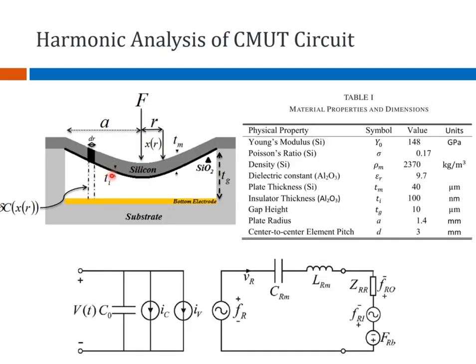All right, now for this cell in which silicon is hanging, it is clamped at the glass posts because it is fixed, it is bonded, and that's how a single cell can be seen as a cross-sectional view. And then you have a bottom electrode which is connected to the external connection pads where you give the electrical signal. You have passivation. In this case, we have alumina passivation, not silicon dioxide, so that has to be changed.